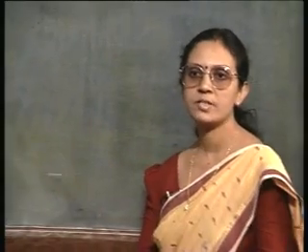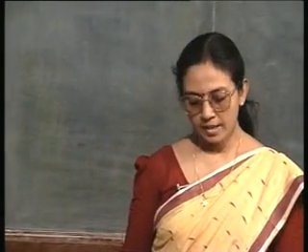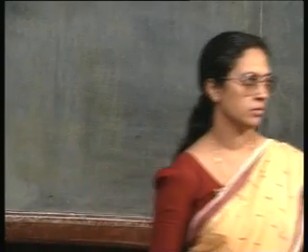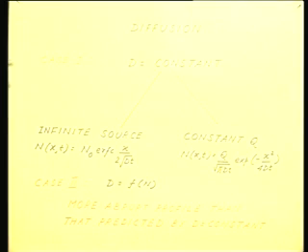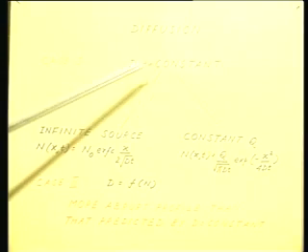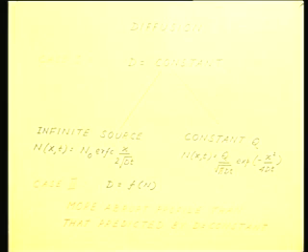Discussion about the diffusion process. So far we have seen that it is possible either to have a constant diffusivity, in which case we will call it case 1, D is constant, and in that category it is possible to have two branches, that is the infinite source diffusion, which will be given by the complementary error function profile, and the constant total impurity case, constant Q case, in which case the impurity profile will be given by a Gaussian function.